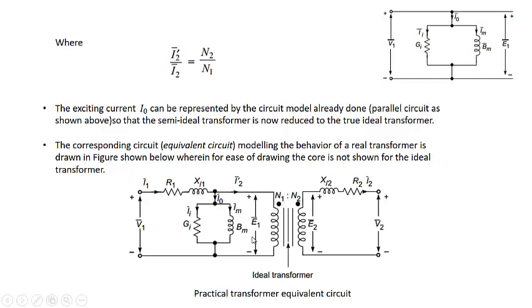And this is the ideal transformer, where we assume there are no losses, no leakage, and no magnetizing component of the current. Finally, we have the secondary side reactances and resistances. So this will be the actual equivalent circuit of the transformer.